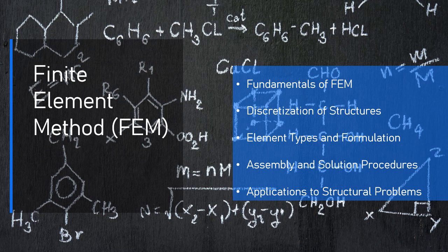4.5. Seismic analysis. FEM is used extensively in earthquake engineering to evaluate the seismic performance of structures. This includes dynamic analysis to predict how a structure will behave under earthquake loads, which vary with time and frequency. Application example: seismic analysis of a tall building. FEM can simulate how the building will respond to earthquake ground motions, allowing for evaluation of the dynamic response, including displacements, accelerations, and forces at each floor.